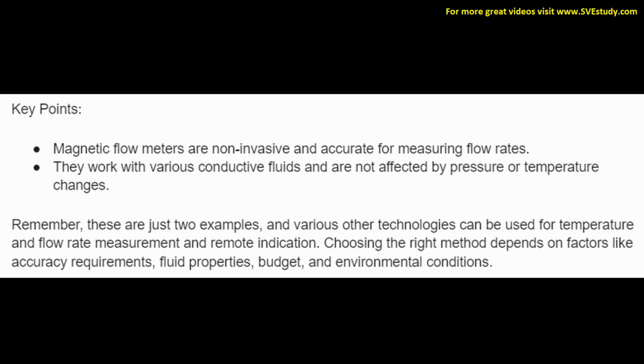Magnetic flow meters are non-invasive and accurate for measuring flow rates. They work with various conductive fluids and are not affected by pressure or temperature changes. Remember, these are just 2 examples, and various other technologies can be used for temperature and flow rate measurement and remote indication. Choosing the right method depends on factors like accuracy requirements, fluid properties, budget, and environmental considerations.